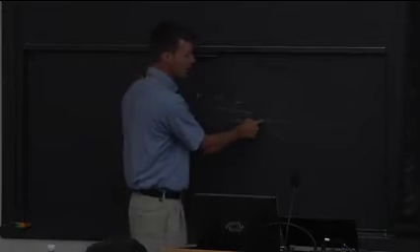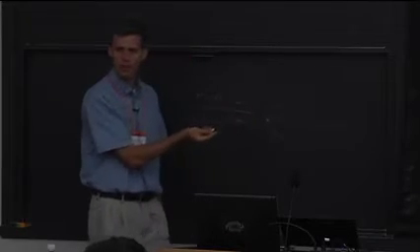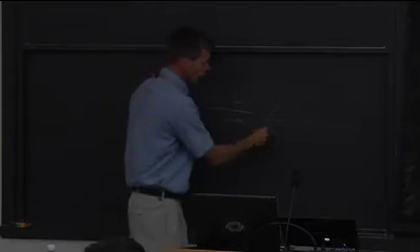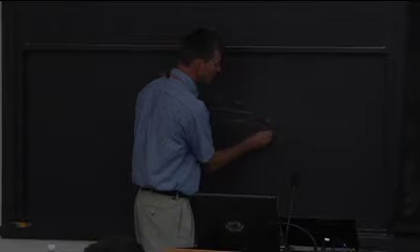But people have gone in and they've realized that actually, the flow velocity at the leading edge of the flame is much higher than the flame speed. How can the flame sit there? And the reason is for the reasons I just talked about. You've got positive curvature, so the flow is actually decelerating.